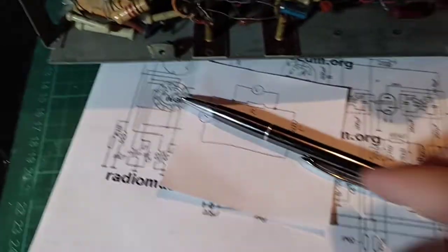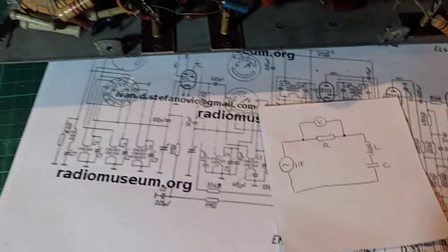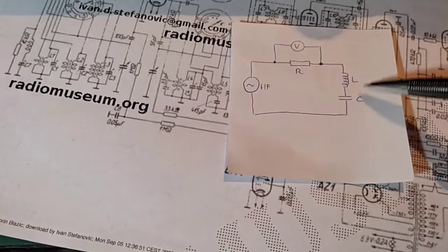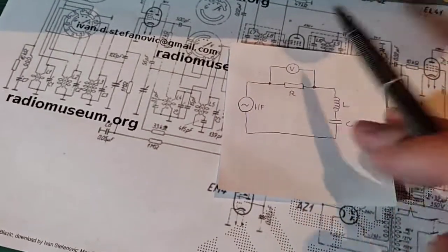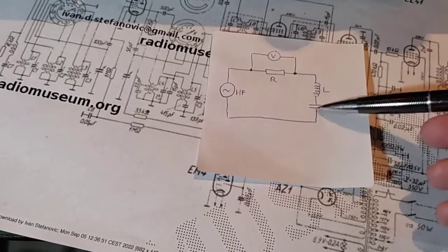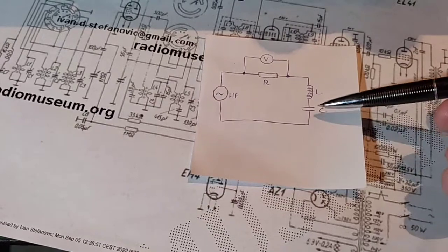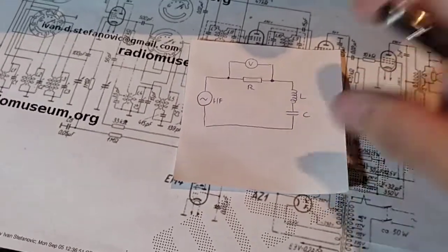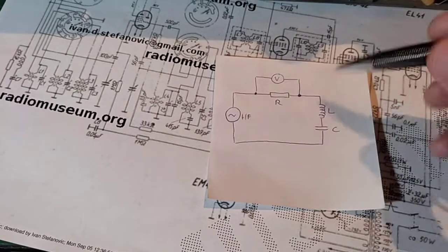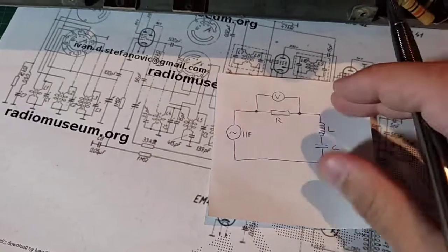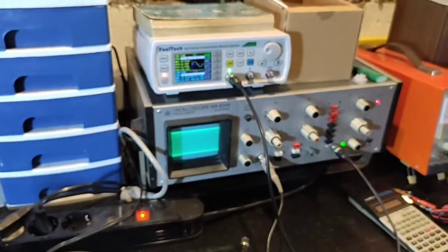But anyway, you saw how simple it was to measure this frequency. I can add some capacitor here, and I can use that in calculations to determine how much capacitance I need to add in series. That would reduce the resulting capacitance, that would increase the frequency, and so on. But that's another story. That was just for you to see how easy it actually is to measure the resonant frequency when you have a signal generator and an oscilloscope.